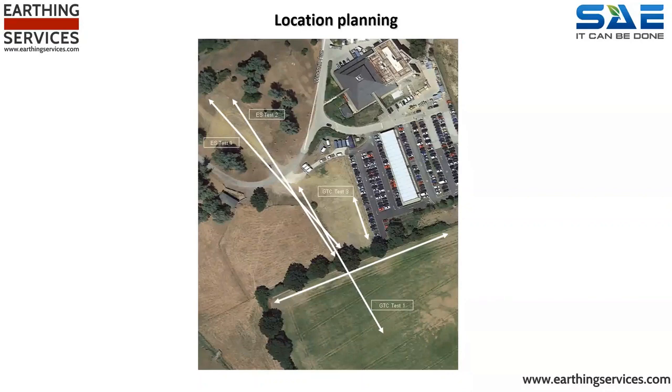From the moment the company receives an order which requires a soil resistivity survey, Earthing Services engineers commence the desktop planning stage of the project. Our trained team knows how to assess the practicality and usefulness of a given area when it comes to undertaking soil resistivity surveys. This can begin by using topographical data, location coordinates, and plotting technologies. In many instances, simply loading up Google Earth will give an idea as to viability of test routes. Although do remember that Google Earth is not live, and as such, do check that the areas selected remain valid.